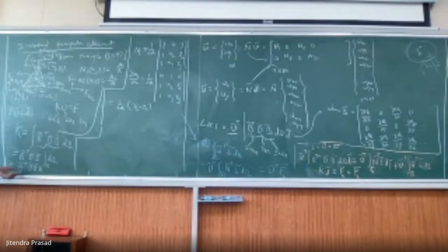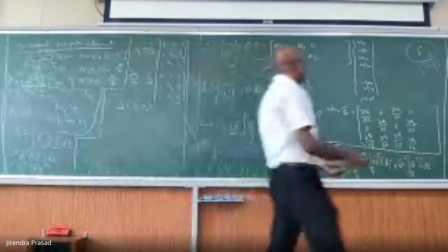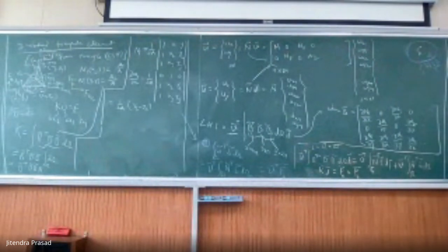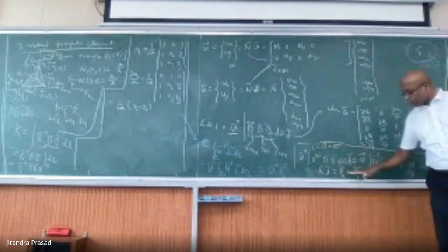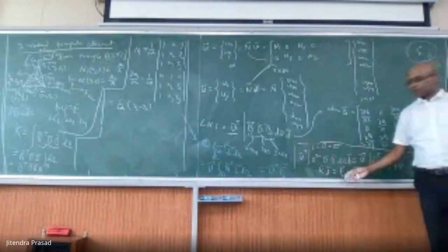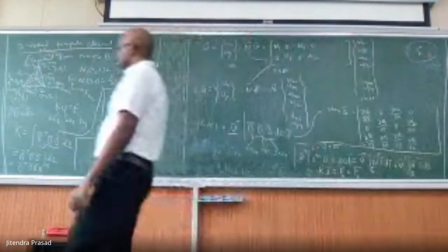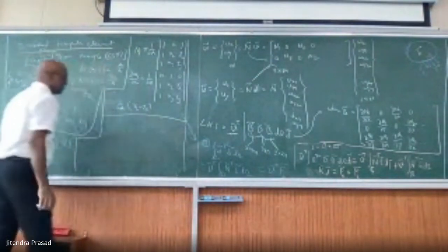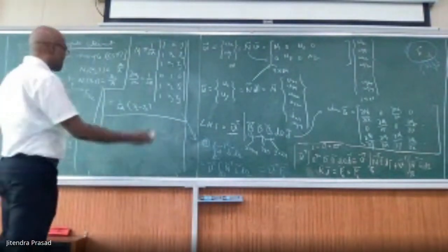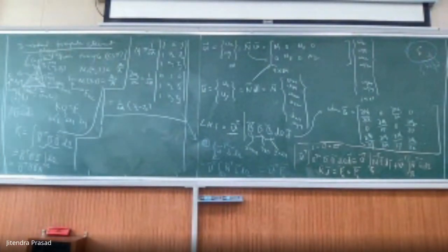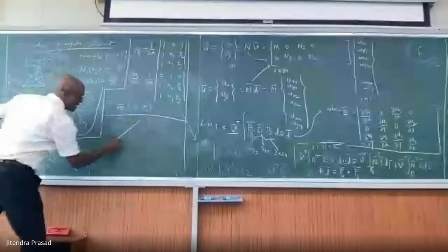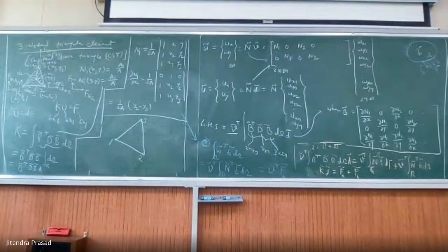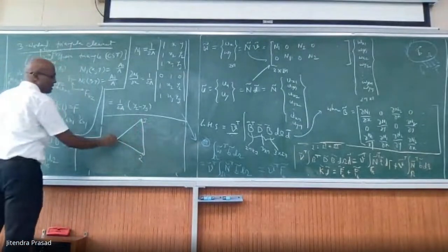Okay. The only thing is you now have to compose the B matrix, and the B matrix is composed this way. That's it. How to compose this is the same way we saw yesterday. As far as forces are concerned, you have the n which is given, and if we have a triangle 1, 2, 3, n1 will be 1 here and 0 here and 0.